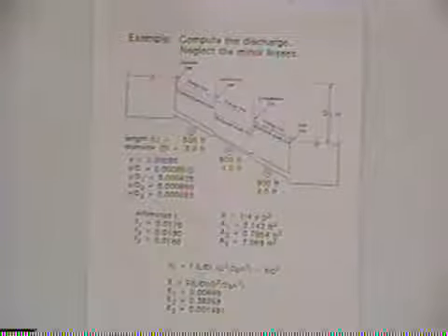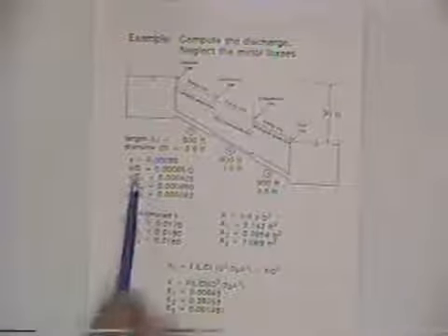And one example for pipes in series and one example for pipes in parallel. Here's the same problem we did before. The only difference is before we connected two reservoirs with one pipe, now we connect them with three. We've got the same 30 feet of difference in water surface elevation, and three pipes in series, each with different lengths and diameters. In this problem they all have the same absolute roughness for use in the Moody diagram to get the friction factor.